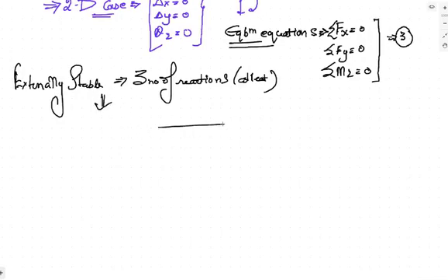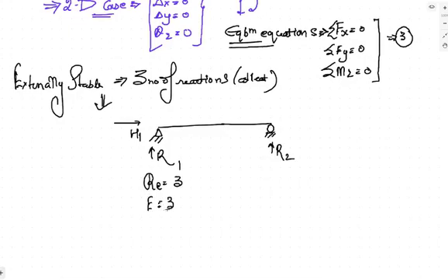For example, if you have this beam, a simply supported beam. In a simply supported beam, the hinge reactions are R1 and H1, and this is R2. It means that the total number of reactions, if you consider the support, is 3. The reactions are 3 and the number of equilibrium equations is 3. If you want to find the stability, it will be 3 minus 3, which is 0. It means this structure is stable because 3 reactions are required and 3 reactions will develop at the support. 3 reactions, 3 equilibrium equations, 3 movements possible and all 3 movements are being prevented.